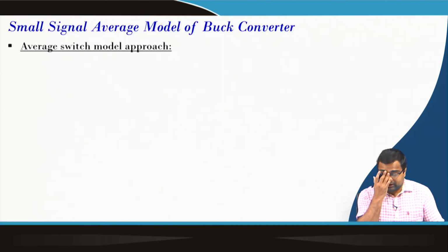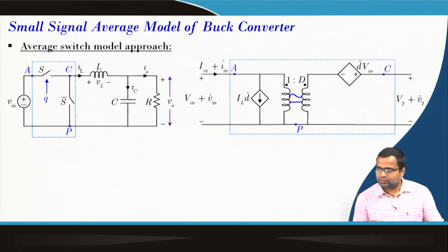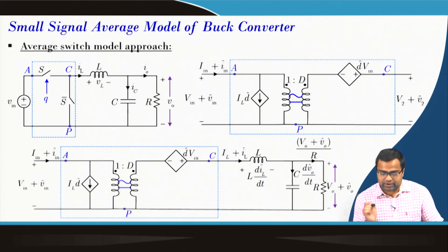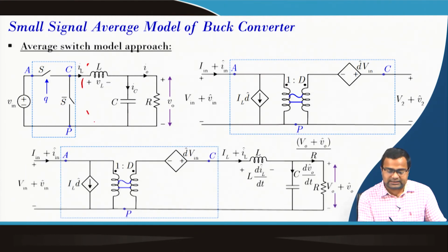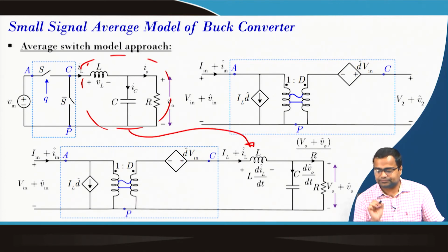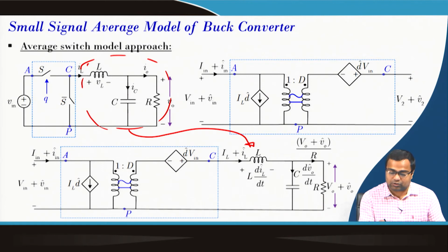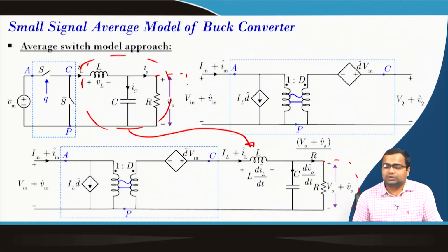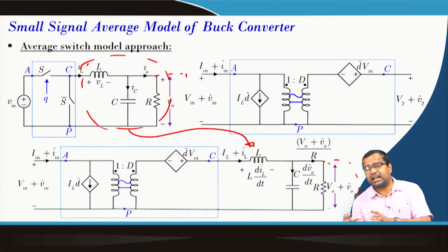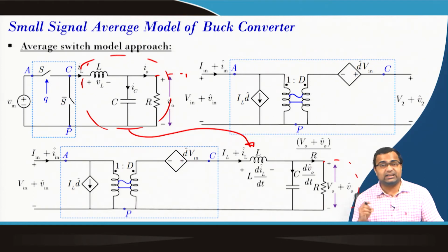Now, for a buck converter, this switch model we have already found. Now, we want to replace it with this inductor. So, this part now we can join back, and the beautiful thing is, if you incorporate a current load, or if you incorporate additional impedance or a filter element, the same model remains and we will not touch this part.